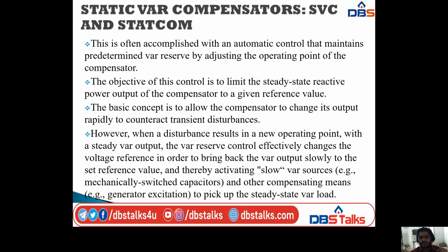This is often accomplished with an automatic control that maintains a predetermined VAR reserve by adjusting the operating point of the compensator. The objective of this control is to limit the steady state reactive power output of the compensator to a given reference value. That's why we are using this characteristic, VAR reserve control or operating point control.